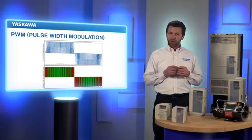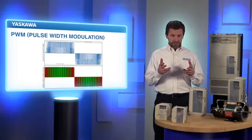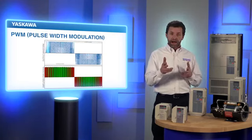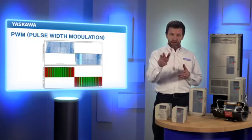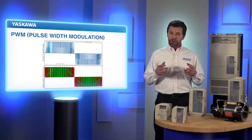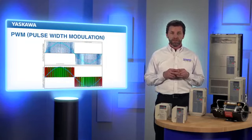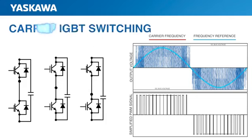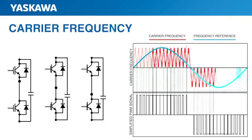Voltage reacts very quickly compared to current, which causes this block-type output. The pulses are high in amplitude, but the RMS, or root mean square voltage, appears equivalent to the motor-rated voltage. You will find motors that can handle this PWM-style waveform tend to be labeled inverter duty on the nameplate. Now, the rate at which IGBT switching occurs is known as the carrier frequency.